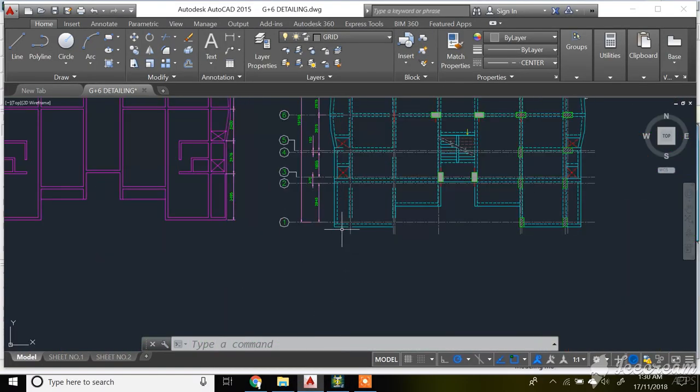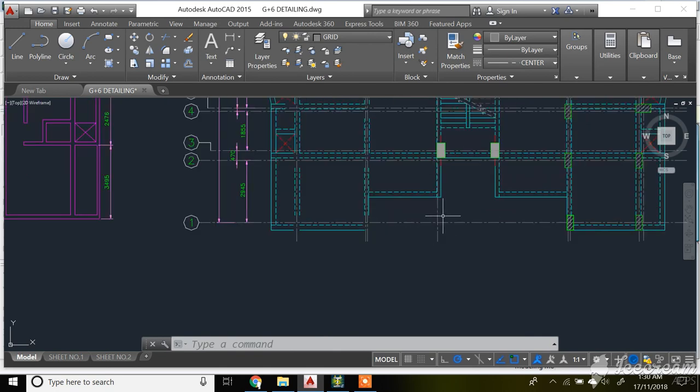Like we are giving a column here, we will now create these nodes. Later on we will delete this node. We will work with this node first because we can easily replicate those nodes. Once these nodes are replicated, we can just delete these two nodes. That will make it very easy to build the geometry, and we can make the geometry within a very short span of time.